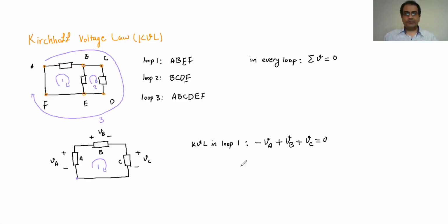When we have a circuit and we want to analyze it, we write the KCL and KVL for all the nodes and all the loops, and then we solve them together, and along with Ohm's law, we can get the voltage and the current in the system. And again, when we are talking about analyzing a circuit, this is all we talk about. Find the current and voltage in the elements or the wires. That's all we want to find. How much current we have in each element of the circuit, how much voltage each element of the circuit has in it.